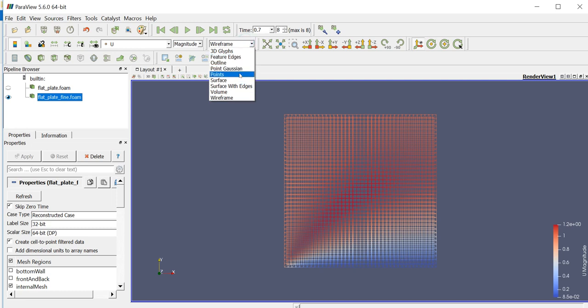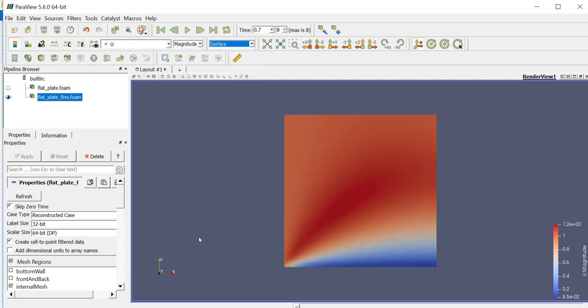So from this we can conclude that the problem of this kind of velocity profile is not caused mainly by the mesh size, but it could be something else. But in this video we have already covered the basics of creating a finer mesh and how to do it in OpenFOAM, and we have found that the mesh size isn't the problem in this case. So let's take a look at other potential issues, and see whether we can find the root cause of this problem elsewhere.